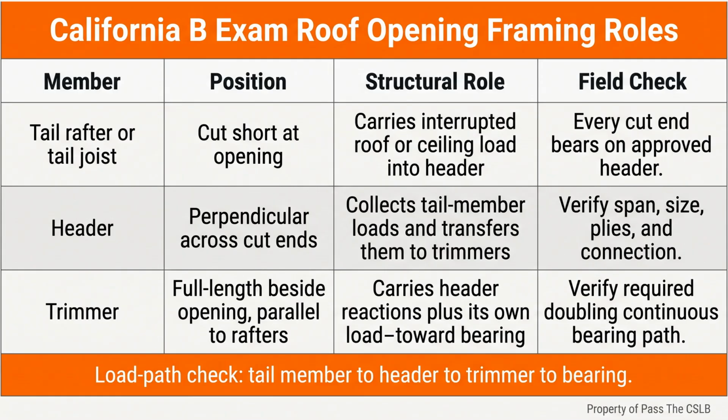Imagine a contractor who lays out a large skylight, cuts first, and plans the framing afterward. The cut ends lose their original support, the roof is open to weather, and the crew is pushed toward a rushed repair. The better supervisory decision is to confirm the approved detail, member sizes, connections, weather plan, and opening protection before the first structural member is cut.